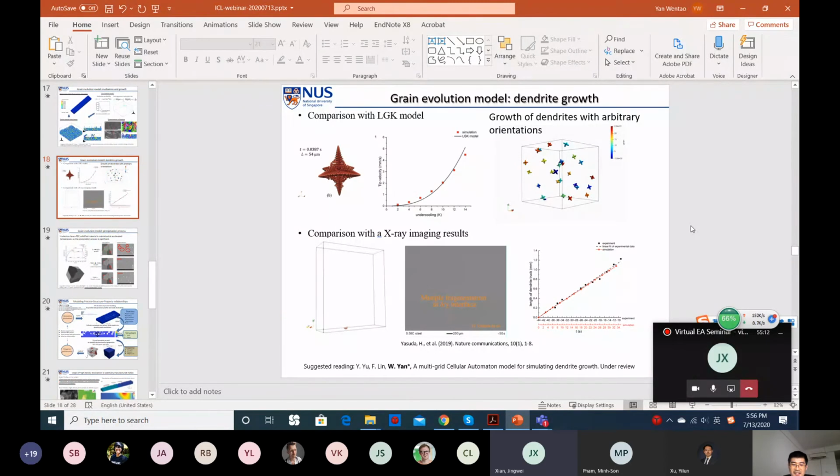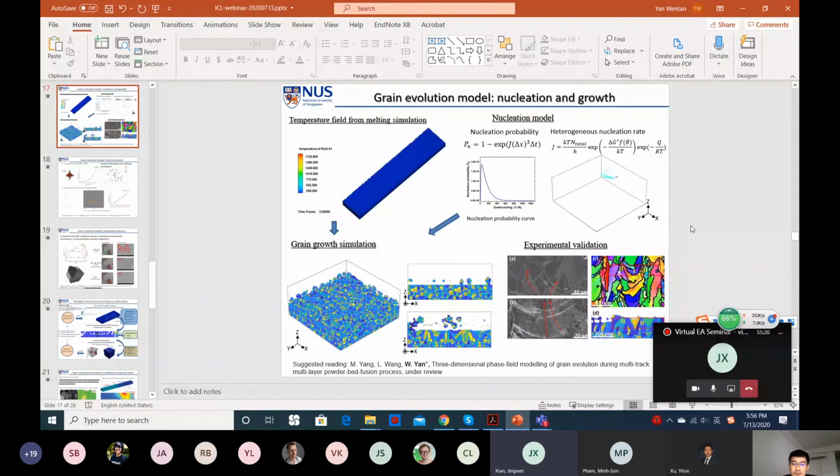Oh. Yeah. Another comment is about your model of nucleation, on the next or previous slide. Here in your model, I think the main factor in the equation might be f(theta), the geometric factor for heterogeneous nucleation. That's my understanding. So how do you determine where the nucleation sites are? Because I believe the particles might flow and are not fixed, so the geometry might change during the scanning. In that case, how do you model where they nucleate?